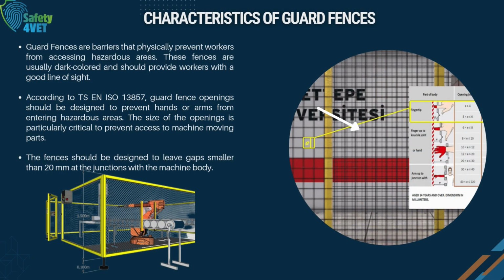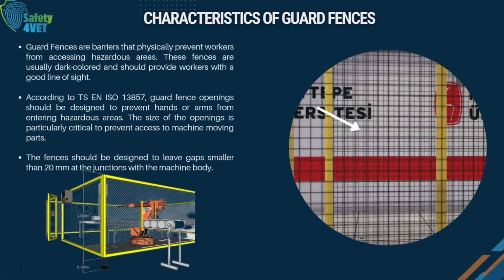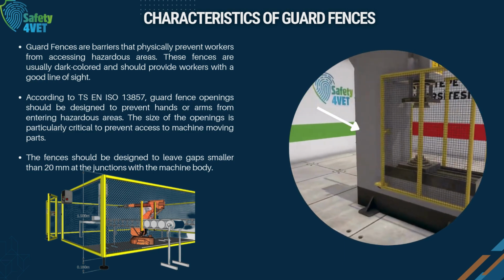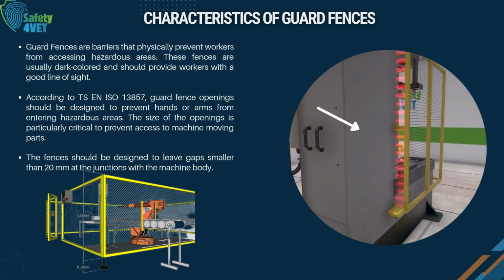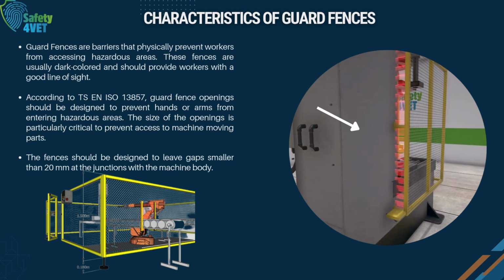All potential hazards that the machine may encounter throughout its life cycle must be identified. Possible risks should be considered at every stage, from manufacturing to operation, maintenance processes, and final disposal. Additionally, malfunctions and emergencies outside of normal operating conditions should also be included in this assessment.